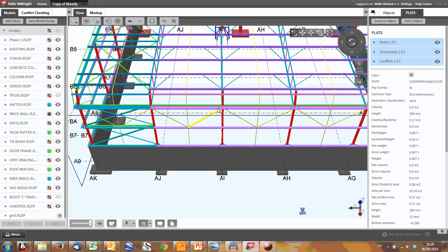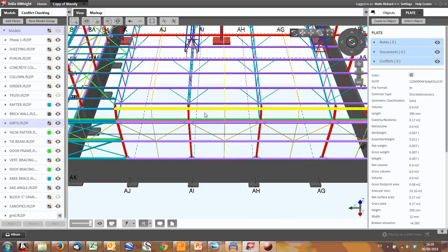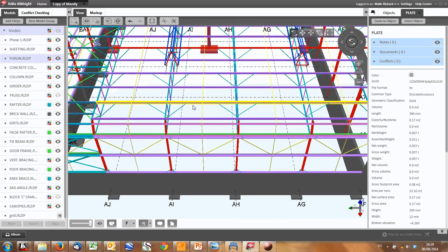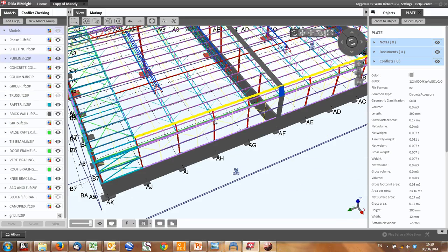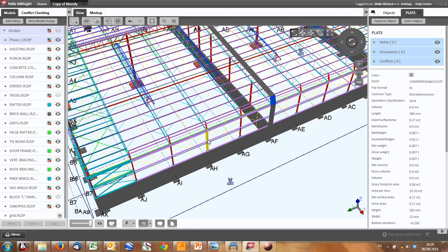On bigger buildings it might go to 9, even 12 meters, but it just means you have very, very big purlins and girts. So there's a balance. Normally the bigger the building, the bigger the bay, etc. But there's a balance between making your girts heavier and having fewer trusses, but then your trusses get heavier as well. So there's an economics in this.